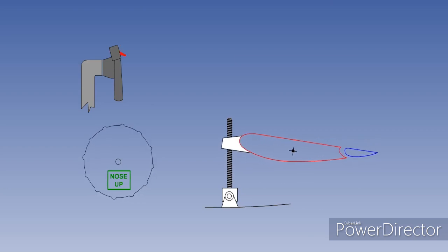However, there is a drawback associated with the increased power of the variable incidence trimming tailplane. If the tailplane were to change its incidence without being commanded, the pilot could not stop the aircraft from pitching out of control because the elevator is much smaller than the tailplane. This is known as stabilizer trim runaway, and safeguards have to be incorporated in the design to prevent it.